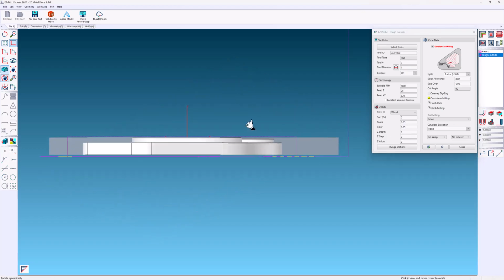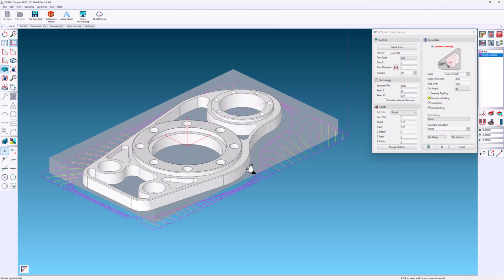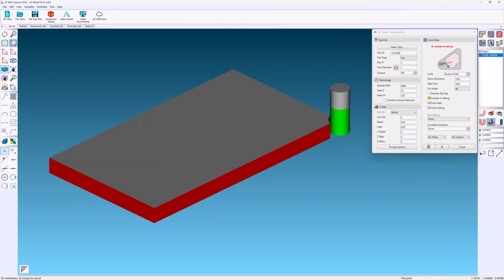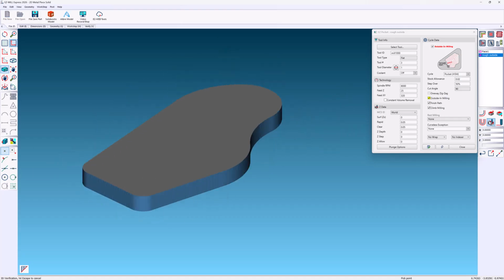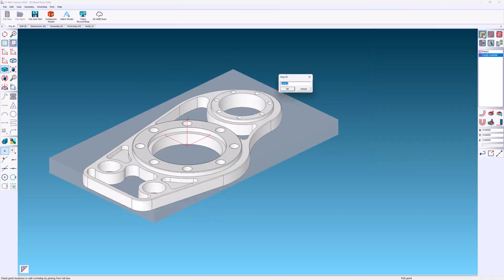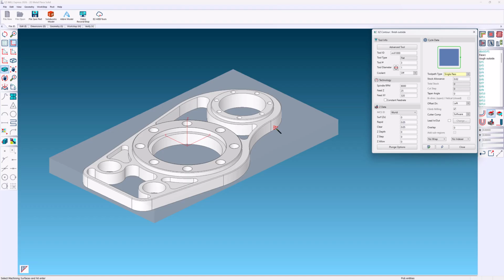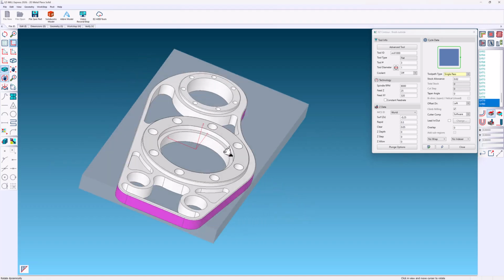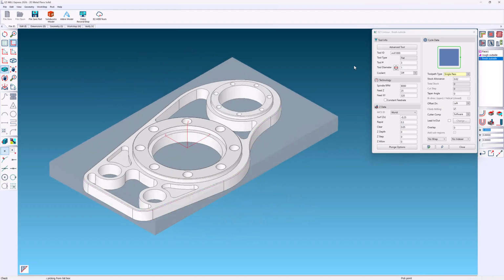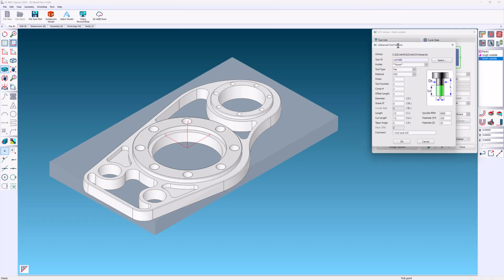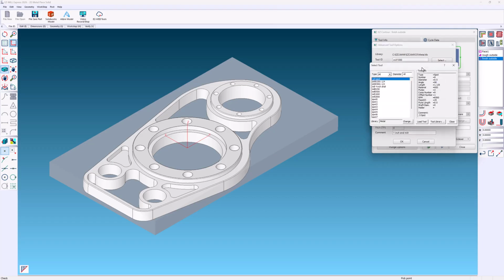As you can see, the toolpath is below the edge of the selected surface, making for a clean cut. Here's a quick look at our high-speed machining. For this contour operation, select a single vertical wall, and all the associated faces will chain. Let's keep putting that library to good use. Again, if you have something quick to program, maybe change the values on the fly instead.